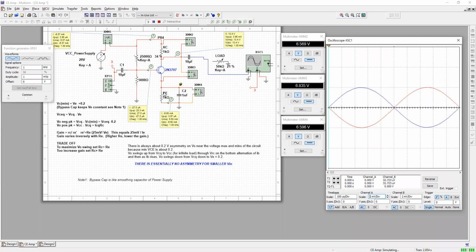And so the RE resistor is actually looking practically smaller. If you were to think of it as two impedances, two mysterious impedances in parallel, there's more current now that's going to flow through RE because C2 is a larger impedance.